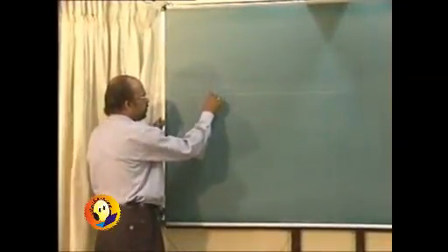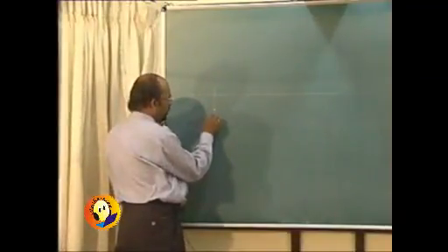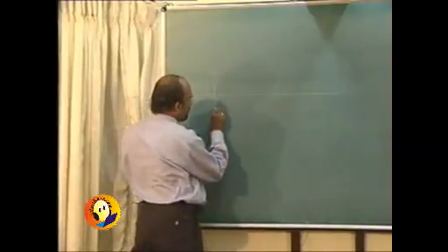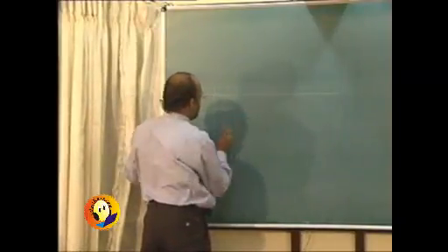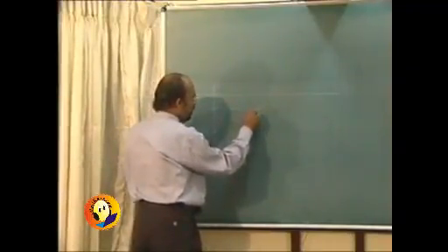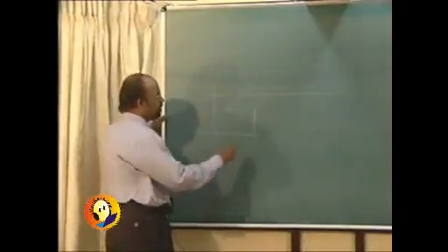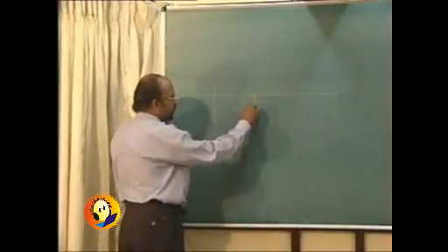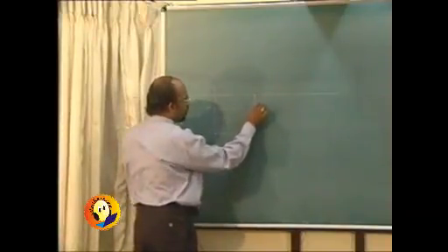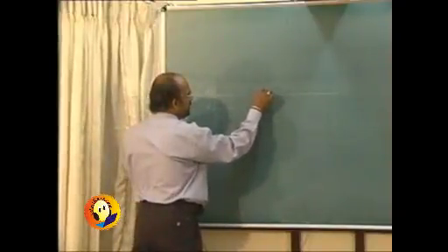Line of rotation is drawn perpendicular to XY, on which we will have 2 points spaced 30 apart. And then we are required to draw the rectangle of side 50 here. So this is the rectangle of side 30 by 50. True shape is drawn in plan. Name it as, say, A, B, C, D. So this will be A dash, B dash, C dash, D dash.